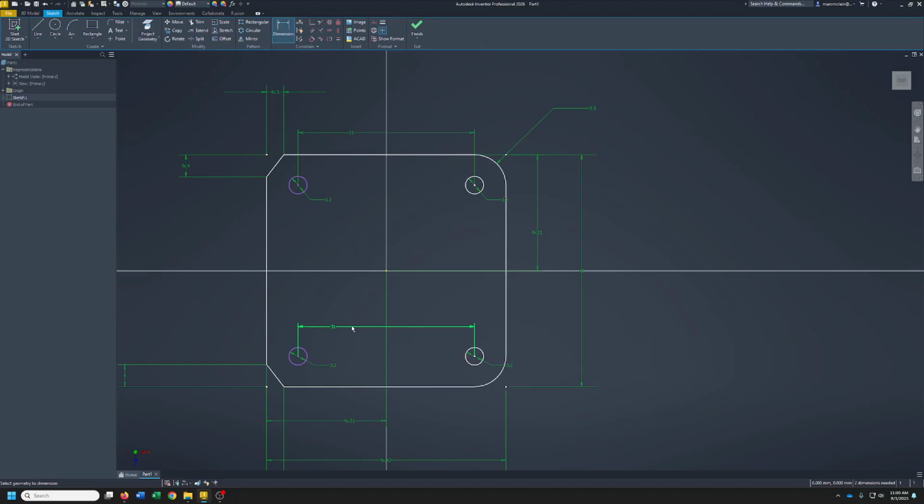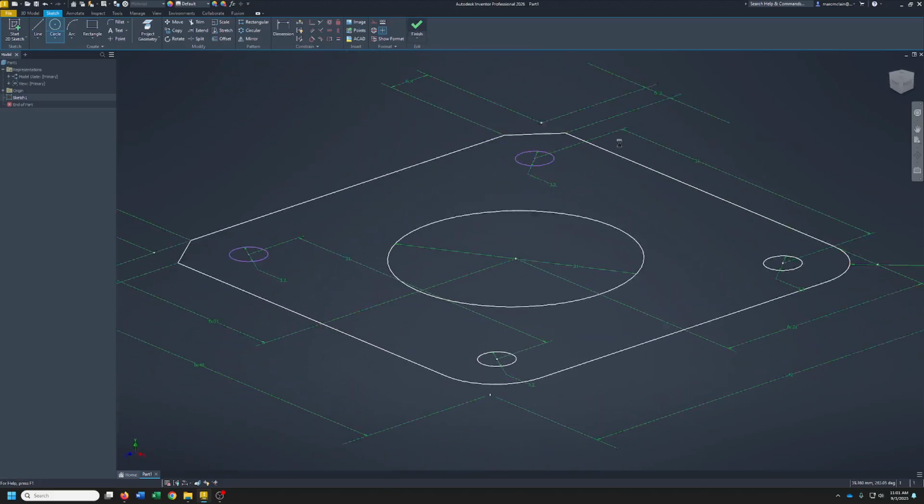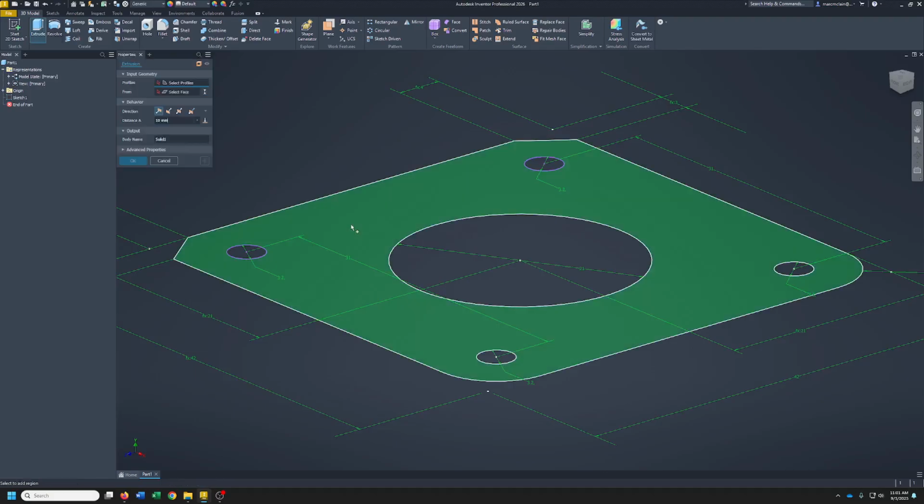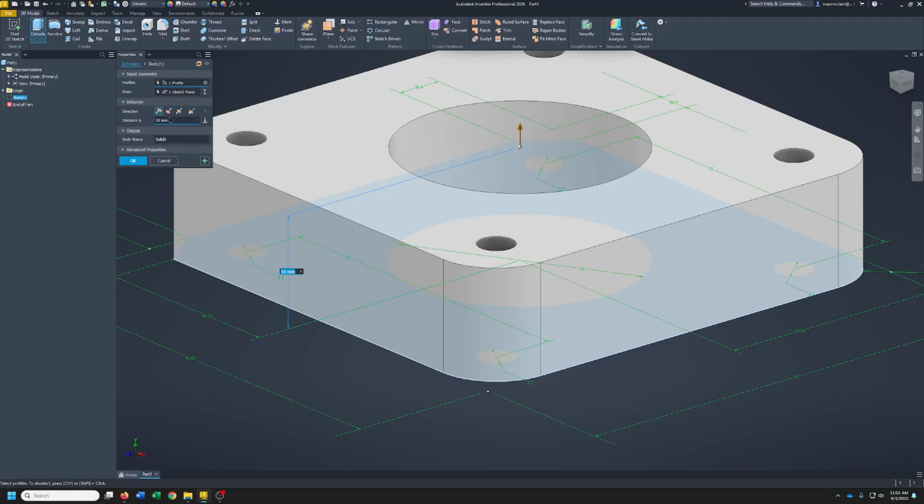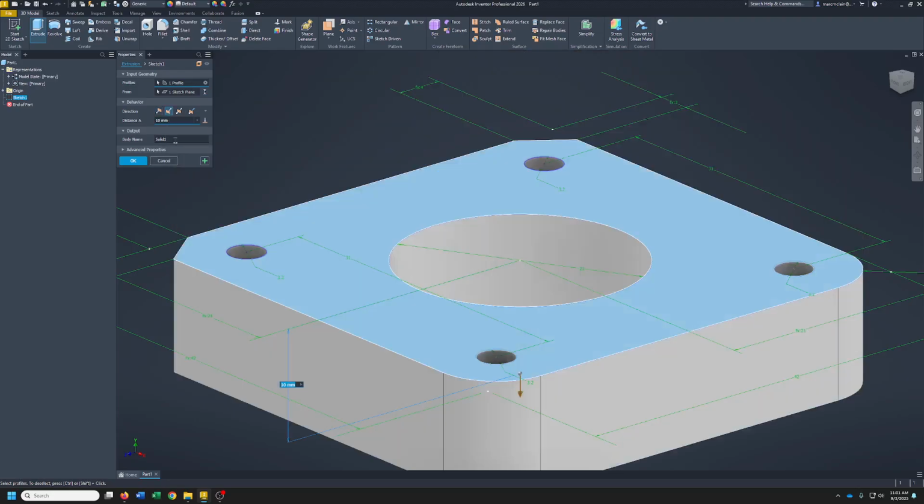All right, so that's got the base. And we got this one big hole in the middle. It's a diameter of 21. And it's right in the center. All right, so we're set for diameter, so 21. All right. So finish that sketch. All right, now we're going to extrude. I'm gonna go the other way. We're gonna go underneath. 4.